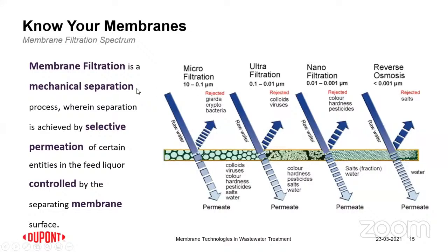So if you look at this, you see four types of membranes based on the pore size. I was talking about nominal pore diameter in the previous slide. So microfiltration has an effective diameter in the range of 1 micron. That's the reason it's called microfiltration. And ultrafiltration is in the range of nanometers. In the case of nanofiltration, it's 10 times smaller, and reverse osmosis 10 times more.